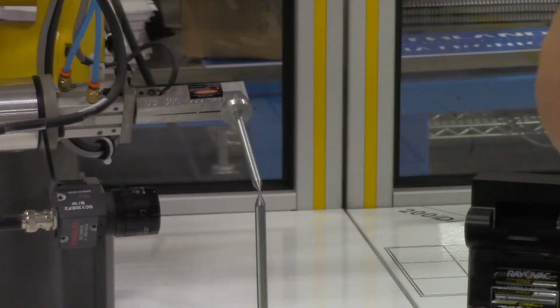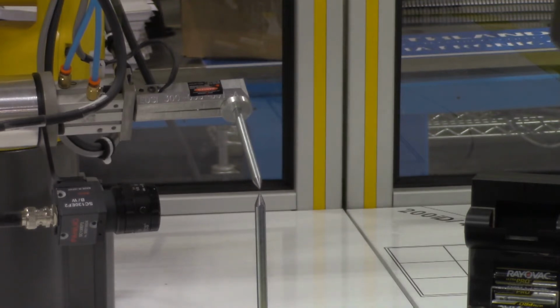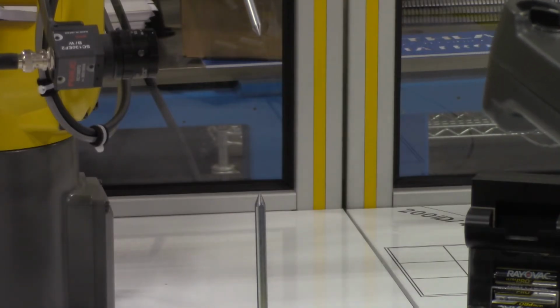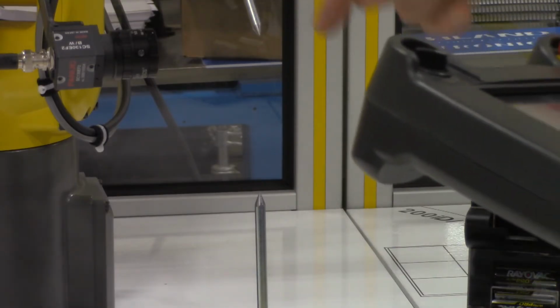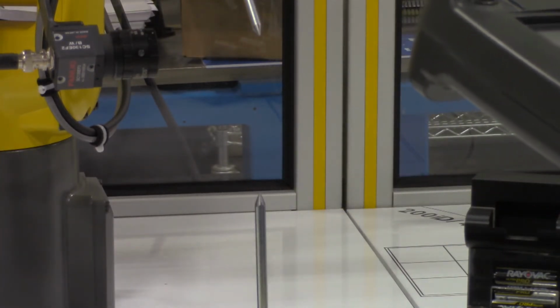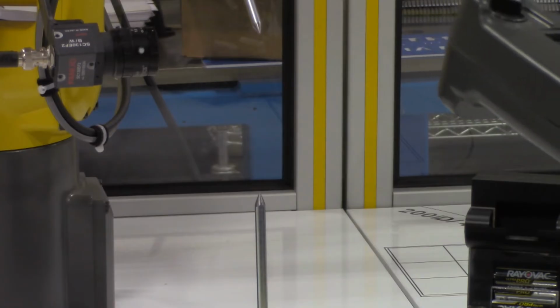So back to the robot, we'll do some more jogging around. Let's see, we're going to jog it in joint mode for just a second here. Maybe not, maybe world mode for a little while. I'm going to bring my z-axis up so I got some room to play. Okay, now this is where it gets to be entertaining. I want to rotate a few axes so that this comes in from a different perspective and we can have that point down. So I think I'm going to rotate in joint mode this final axis.